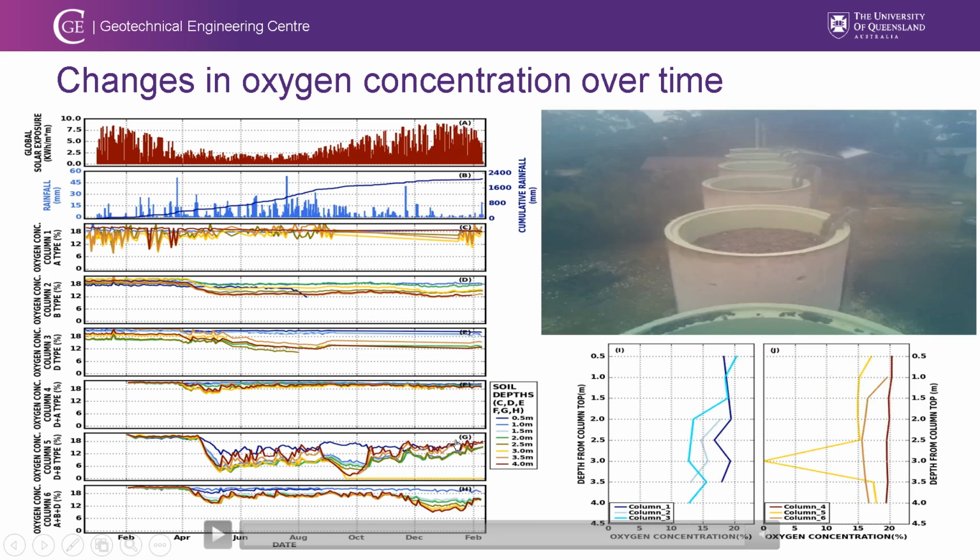So the conclusion is that if we use the coarse waste acid rock core disposal, we are not able to completely minimize the oxygen ingress to the soil. However, if the top moisture content is relatively high, the oxygen ingress could be somehow minimized.